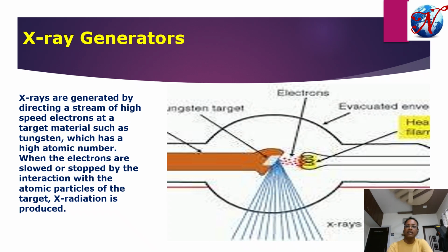And finally, there is a radiation source which is known as X-ray. In general, in medicine we use X-rays of very soft energies. But in our industrial applications, we use X-ray machines with reasonably very high energy. It may vary from 250 kiloelectron volt up to 25 mega electron volt, depending upon the penetrated thickness.